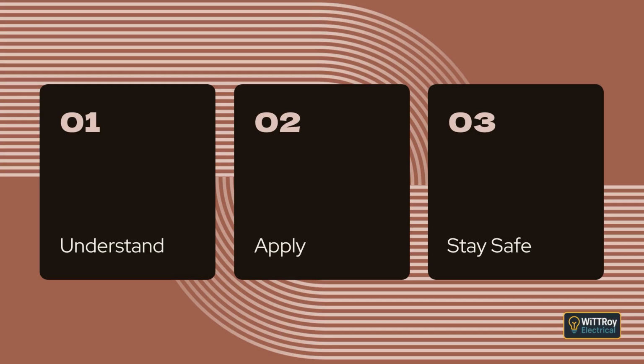There is a note that says this may not always be true for extremely high short circuit currents or for certain circuit breaker types, especially non-current limiting types. If there is any doubt, the characteristics of the device must be checked using Clause 2.5.4.2.